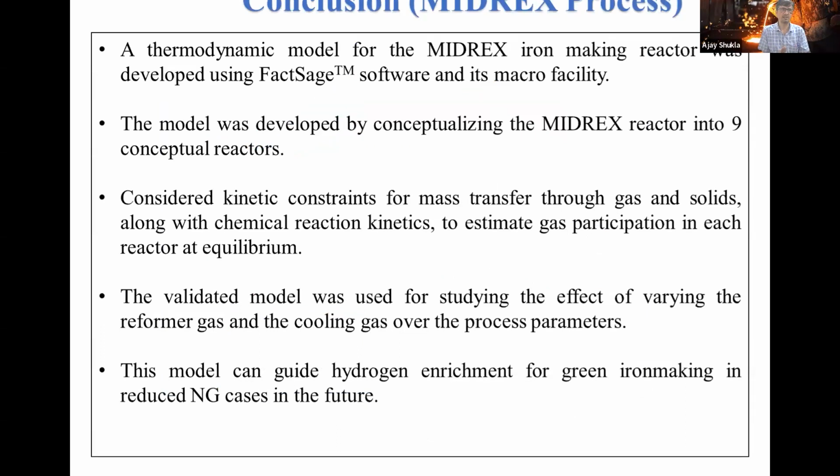So the final conclusion is that a thermodynamic model for the MIDREX iron making reactor was developed using FactSage software and Micro facility. Basically, it was developed by a similar approach, conceptualizing the MIDREX process reactor into a number of equilibrium reactors connected to the flow of streams. And the validated model can be used for studying the effect of varying various parameters. It is in agreement with industry data, and the model can be further developed to study the effect of various other things which I have talked about.